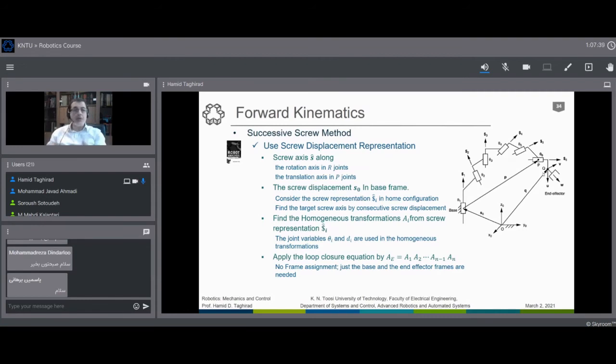So in here, we have the similar thing. Should multiply here, make it equal to this one, but this is, we don't need to have a hundred number of assignments for it and so on, and we can use it that way. How we can do, just remind you the screw representation. You see that I intentionally put it Ai here instead of T. This is the same thing. This is the similarity, the homogeneous transformation, but we call it the screw displacement.